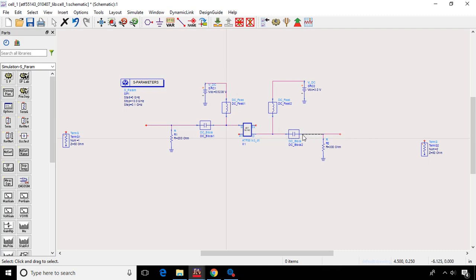But the thing is, we do not have the pads that go in between our capacitors because they weren't specified, and these are just ideal components. They don't have any manufacturer where they come from. If you look for a DC block capacitor, you know they're going to be a really high value capacitor than what the frequency would want.